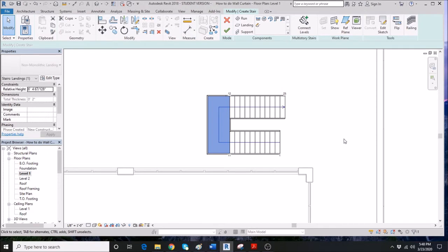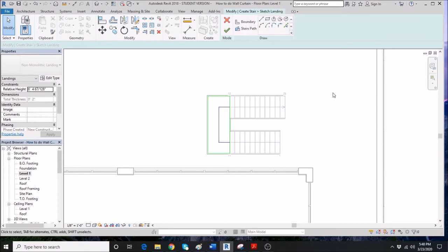Then I want you to go ahead and click edit, this one here, edit the sketch. So I want you to click that. Alright, so I want you to select the arc option. So we have here the arc, we have the center end, but I want you to select the start and radius arc.